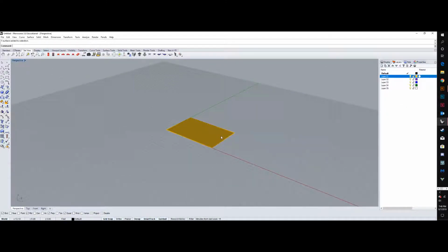It's just a demonstration. So now I'm going to take this surface and turn it into a three-dimensional object with a command called extrude. Notice that it says curve on the end, CRV. That would be for extruding a set of lines, but we are not doing that. We have a surface selected, so we're going to do SRF for surface. Now you can see that it's wanting to extrude this. I can set the distance now. It's saying right here in your commands, extrusion distance, and it's asking for that.